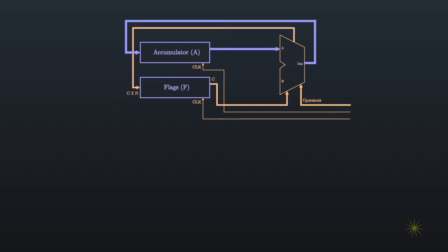It is used to store the results of the status bits from our arithmetic logic unit. Note that we only have 3 status bits, but each of our registers have 8 bits. The other 5 bits in our flag register will therefore be set to 0. In addition to our accumulator and flag registers, we need a way to load results into the other input of our accumulator. So we'll use what we call a bus.